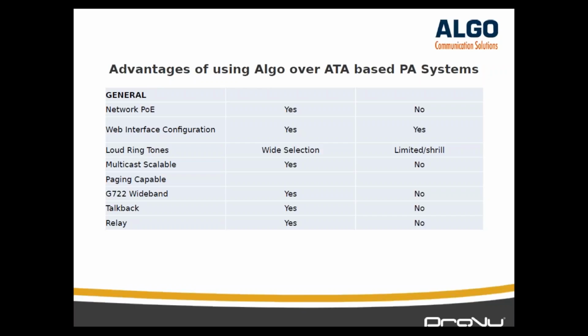So you have to give the customer the confidence that what you're installing will work. The fast way of doing this is to say, we will put an ATA in here and there'll be an analog telephone and you'll be able to still make pages. If the customer says to you though, well, hang on a minute, I'm going to have 2 telephones here, one to make pages down there and another to make pages through my new all singing, all dancing IP system, I'm afraid the answer when using an ATA is, yeah, sorry about that, but that's how it is. With our solution of the 8301, this removes the need for the ATA.